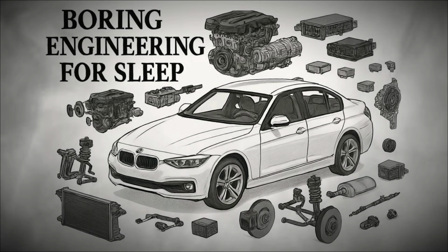Around this cage are crumple zones, which are areas of the car deliberately engineered to deform and absorb energy during a collision, by allowing controlled deformation at the front and rear. Crumple zones slow down the deceleration experienced by occupants, reducing the forces on their bodies.